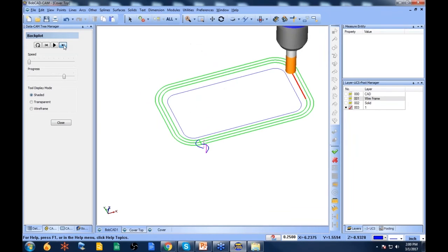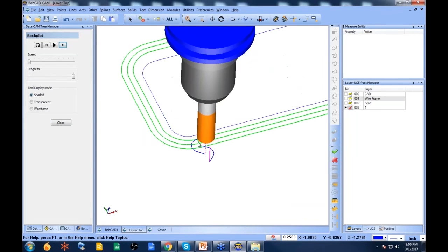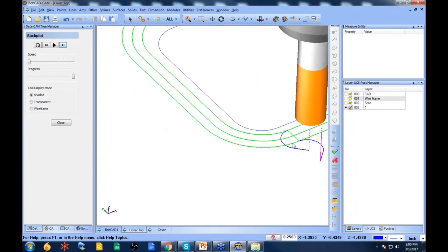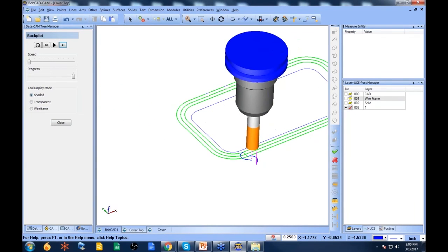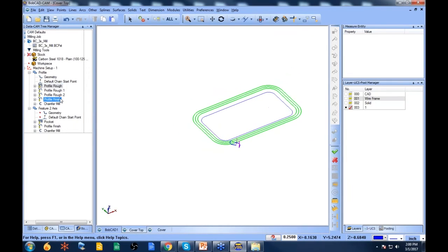A lot of times, instead of using side roughing, I would use an open pocket instead, and the main reason is this tool engagement here. When it goes from one pass to the next, the adaptive pocketing or open pocketing is going to give you a little smoother transition. Depending on what you're working on, not necessarily the worst thing. So that's the first one, side roughing.